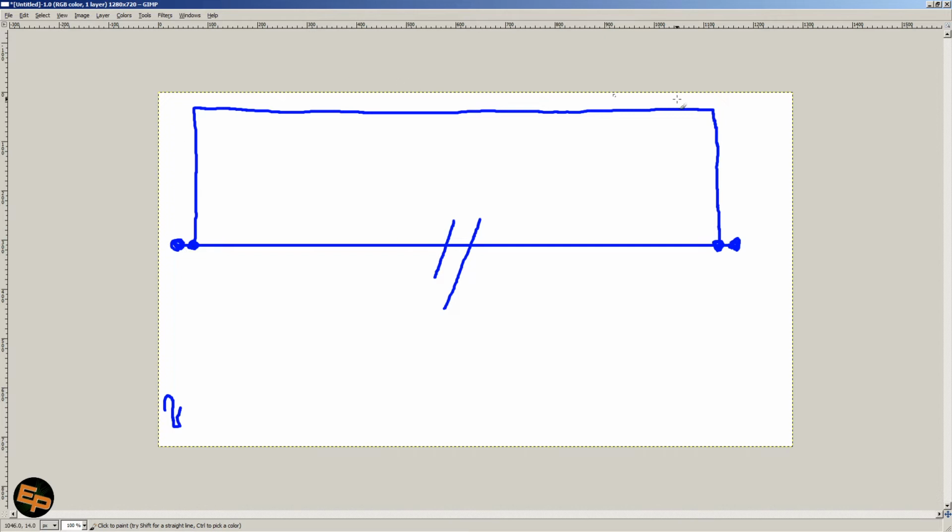Well, it's not impossible to create a second circuit in parallel so that current will still have a path to flow, and then cut the first wire and insert the existing wire through the toroidal core, and then once the new connection is made, remove this extra wire that you put just temporarily, and that's it.